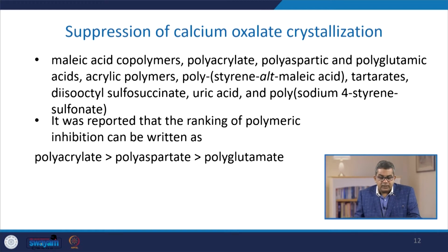Maleic acid copolymer, polyacrylate, polyaspartic and polyglutamic acids, acrylic polymers, polystyrene alternate maleic acids, tartrates, diisooctyl sulfosuccinate, uric acid, polysodium styrene sulfonates. It was also reported that the ranking of polymeric inhibition can be written as polyacrylate, polyaspartates, polyglutamate.